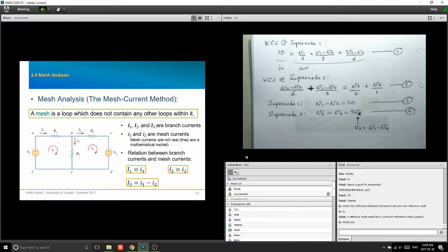Well, the whole point, you have to remember that what physically happens in your circuit is the current flowing through the branches. That's what's real. That's the physical, right? So I'm trying to model that using my mesh currents as a modeling tool. So how do I relate this current capital I3 with those two currents flowing round and round like that?